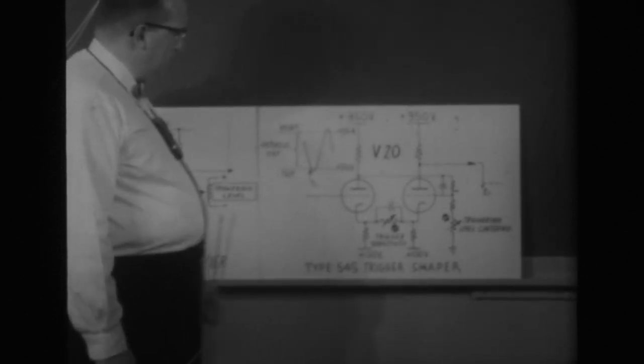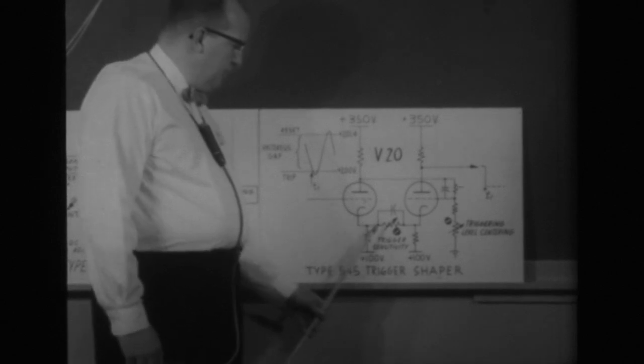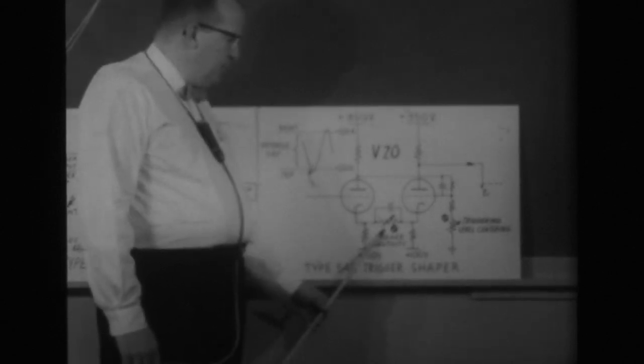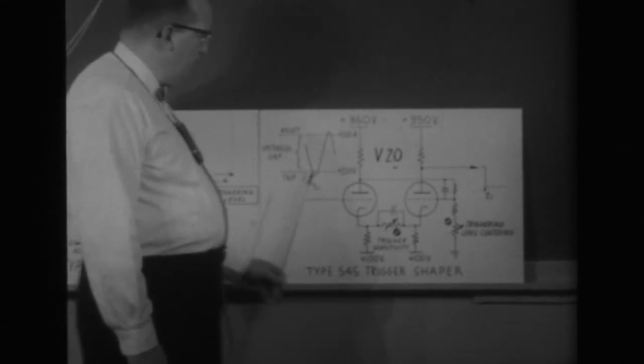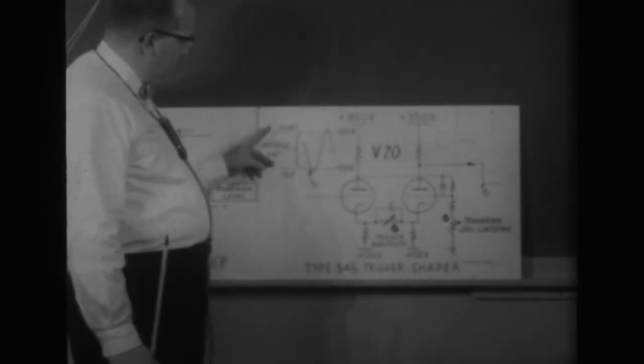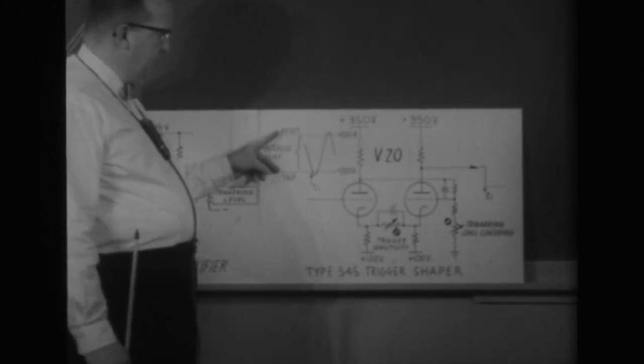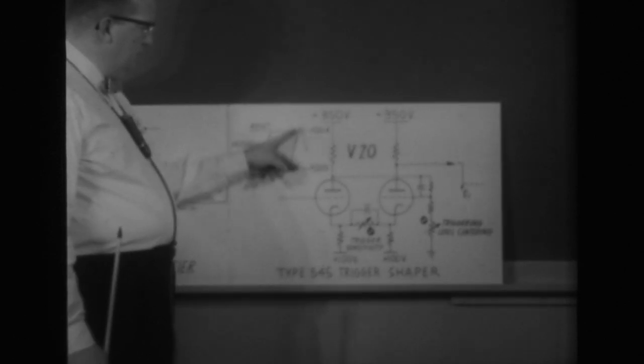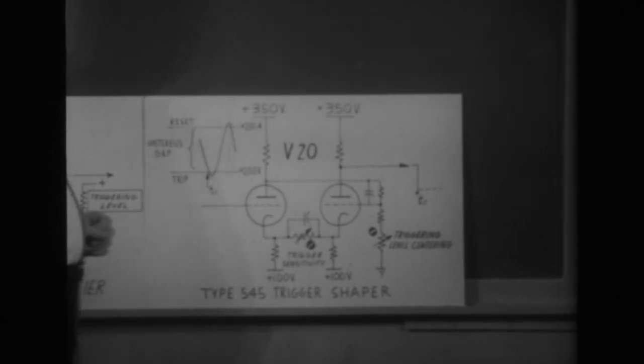Next, we proceed to determine the correct setting for the trigger sensitivity pot itself. And that's done by measuring indirectly the hysteresis gap in volts. In other words, we want an adjustment here where this gap is set to something like 1 2/10 to 1 4/10 volts as shown here.